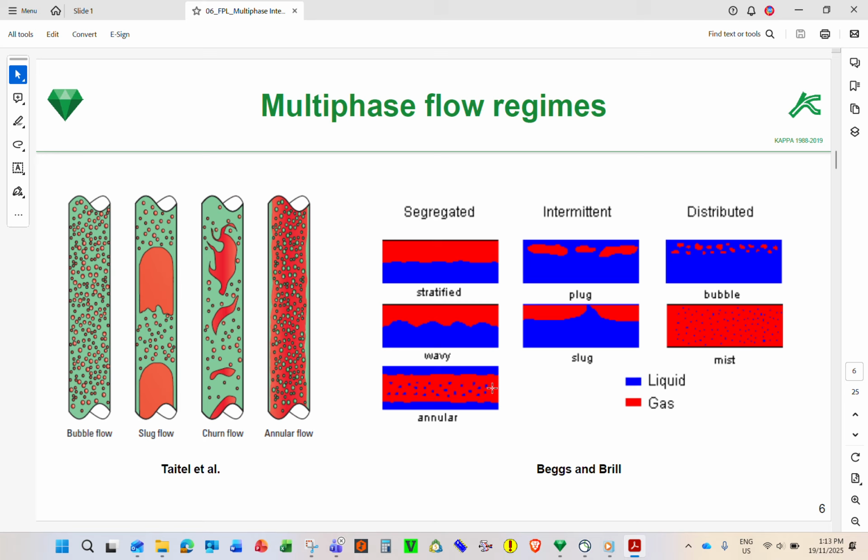Or it might be something like intermittent. If the rates are high and the velocity of both phases is big, then you will have a continuous flow regime. But if you see a small rate of gas, maybe like slugs of gas on the top side. Or you might have a bigger slug coming in, and then no water, no gas, and then gas again. You might also have smaller bubbles like this. So you might have some different stuff.